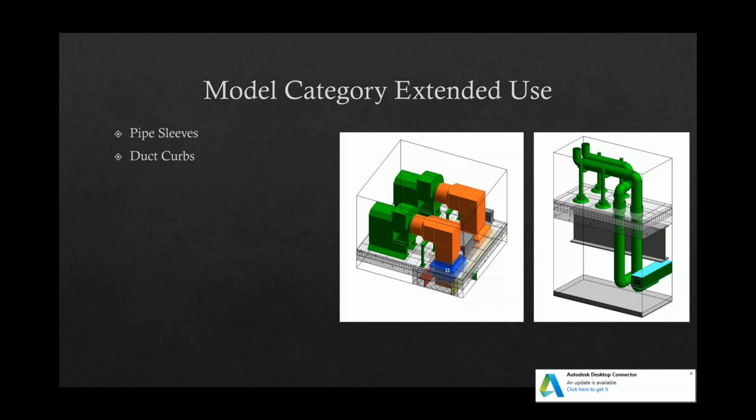So these were instances where, for simplicity or making sure it stayed hosted to the rest of the run, I actually modified a pipe fitting or accessory to make a pipe sleeve that would stay in line, and modified a duct union to make a curb. So again, it can be done. It's helpful for the visual and keeps things connected and moving together. And it looks pretty nice.